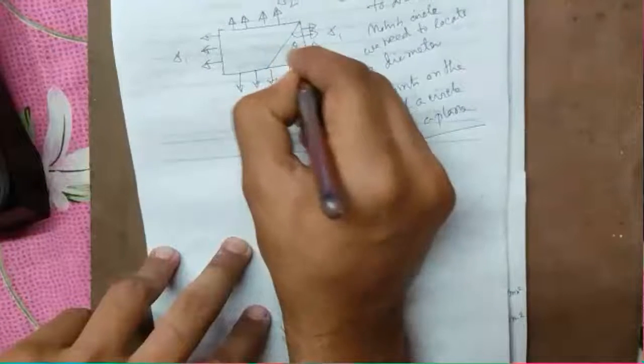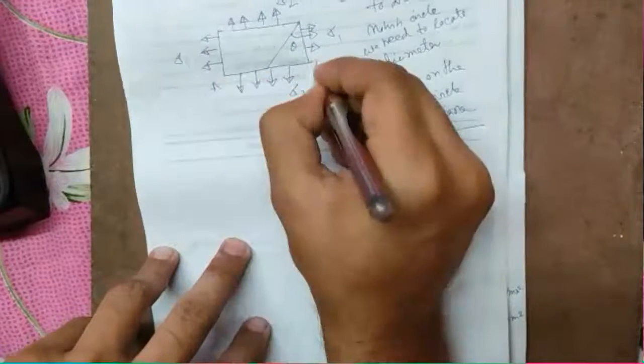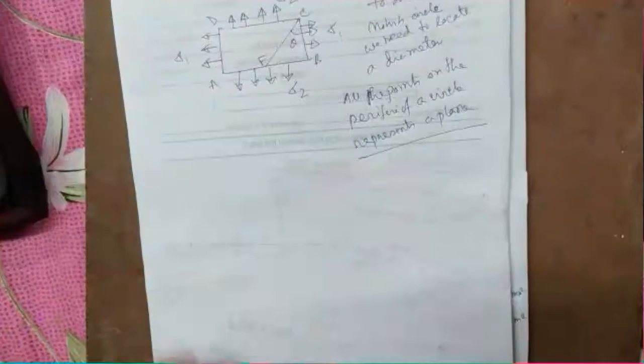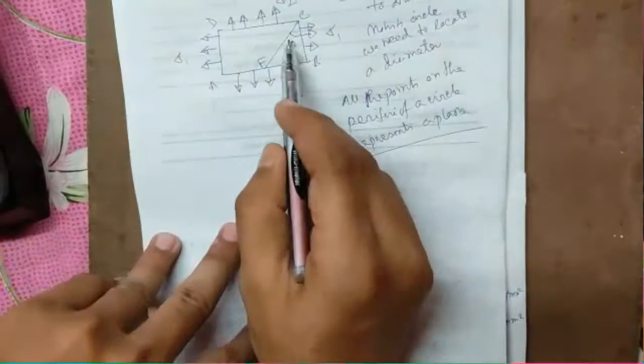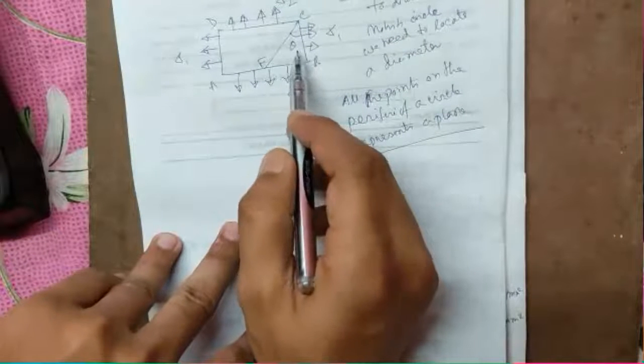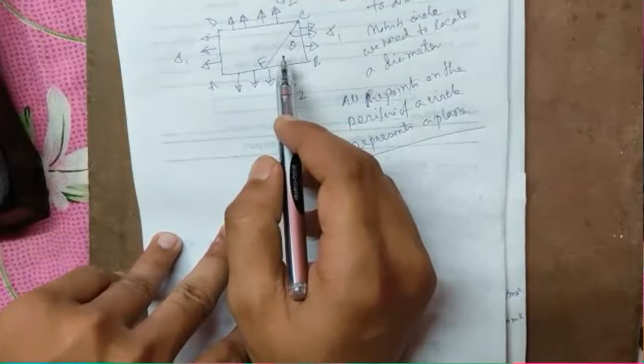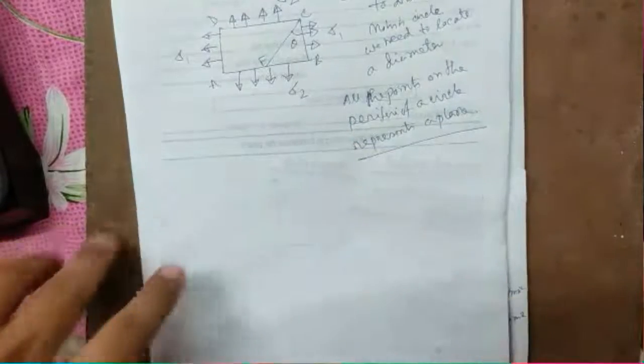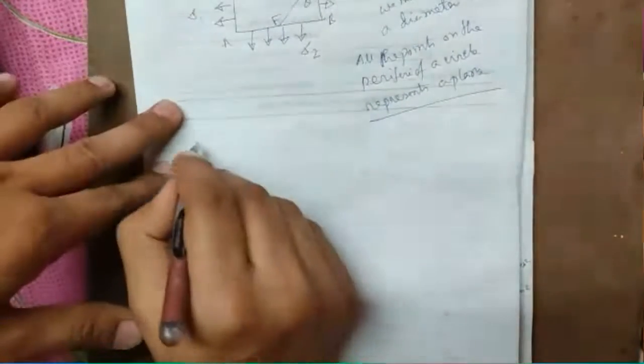Which plane? Planes of different theta. So A, B, C, D, and this is CF at an angle theta. So for changing theta, we will get different planes, and those planes are actually the points on the periphery of the Mohr circle. Now we draw a coordinate system.